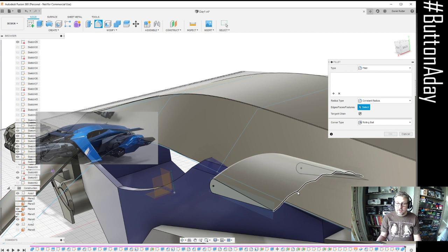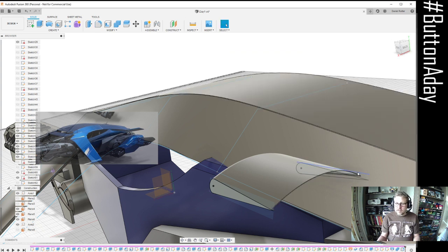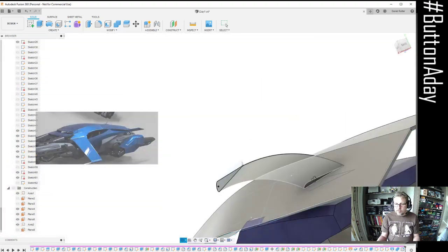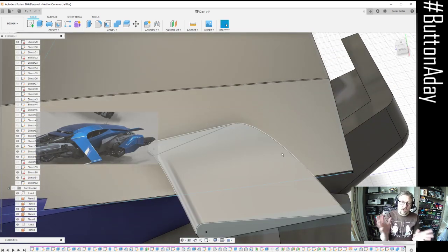But we can also add a small fillet or a chamfer to that pointy edge. In production, you don't really want anything ever going down to a complete edge unless you're making a knife blade or something like that, because the material will get so thin at the end that if you are printing it, it will become brittle and fall apart. If you are machining it, same thing, it's just going to disappear and fade. So even if you add the smallest of little rads on there, say at this point if it was 1 mil, suddenly it crisps up in the drawing as well because it's got more geometry to deal with, and it will just save those things from just tapering away into nothingness.